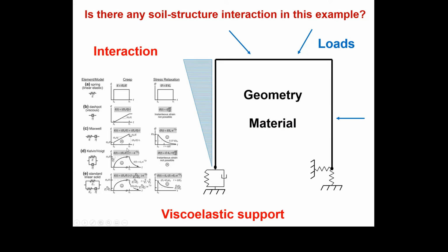We are going to introduce more and more complex equations, because this is what we call viscoelasticity, which you have probably covered in some other modules in structures. When we have this kind of behavior between deformation and time, we have what we call a viscoelastic model. So this is more complex and can probably be shaped closer to reality, but we're still saying that the soil is rigid, because these represent only the interaction between the structure and the soil.